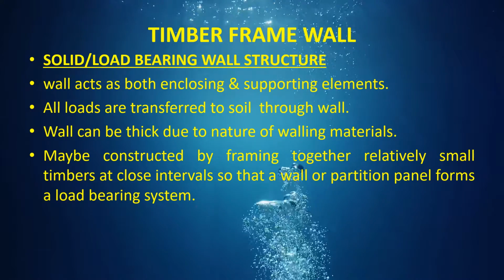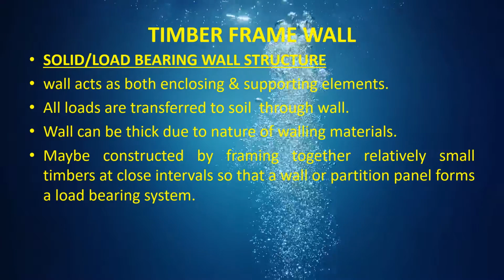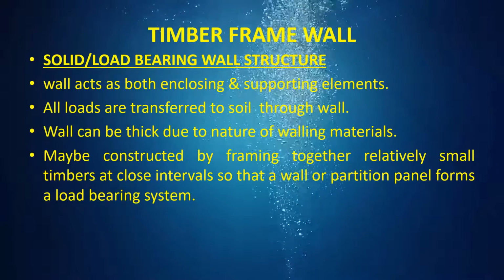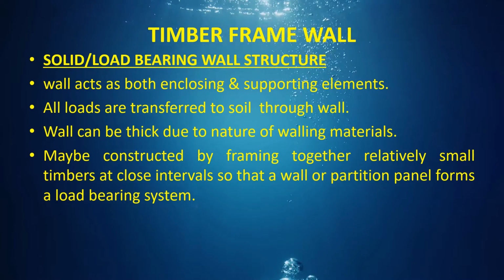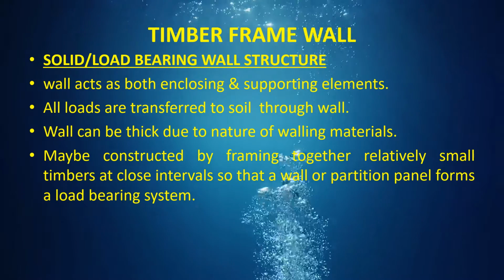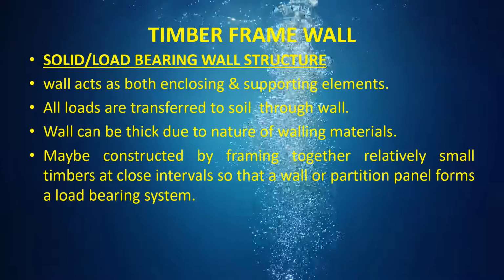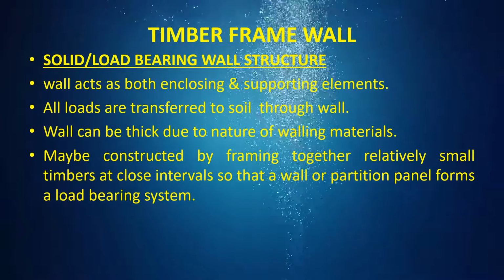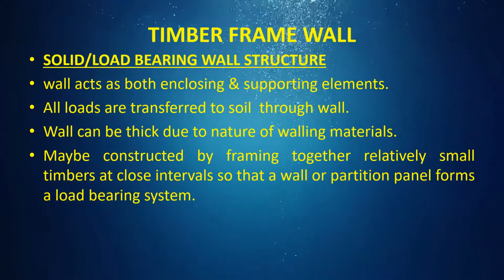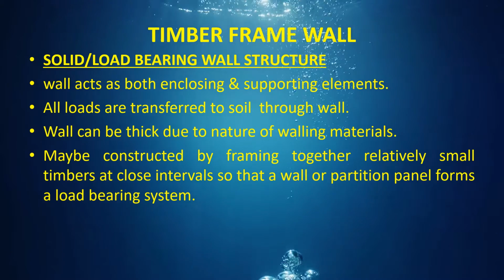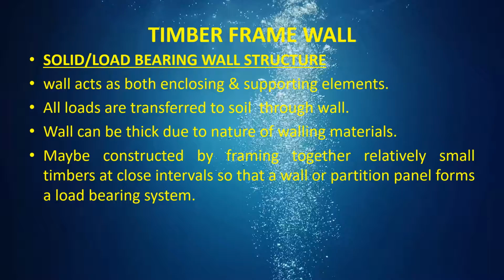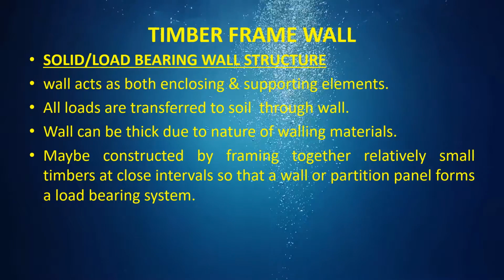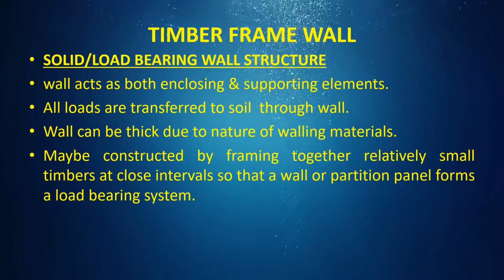Timber frame wall is a form of frame structure but without columns and beams acting as primary load-bearing members. The wall itself functions as load-bearing because there are no columns and beams. The term frame wall is usually applied to an external timber wall involving in its construction appropriate cladding and insulation.